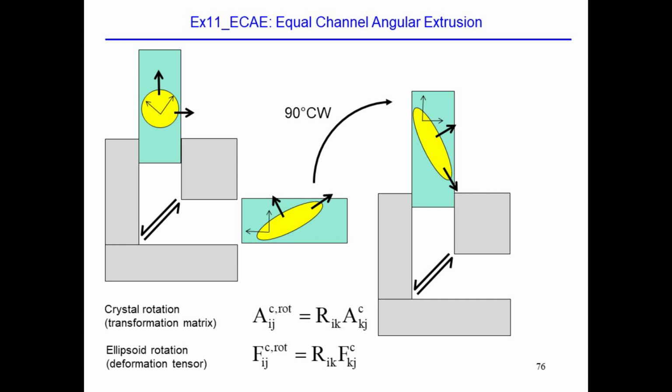What that does is change the direction of the deformation, or of the shear, with respect to the previous structure that you were deforming. So it's not accumulated shear. It could be shear and reverse shear, or shear and transverse shear. Every time you do the rotation, you shear in different directions. You have three different possibilities, and you can keep doing that for 16 passes, let's say.